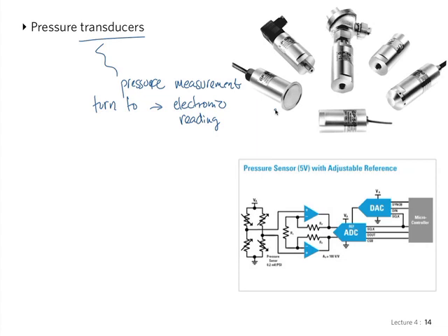To be able to have a control loop of that sort, obviously, for your pressure measurement you can't just rely on a column of liquid, because that requires a human looking at the column and reading a measurement. This requires an electronic signal, and for an electronic signal, we need to use a transducer. Some of these devices are based on what's called a piezoelectric material. If you're interested, you can look this up on your own time. But piezoelectric material basically can generate an electric potential in response to an applied stress.